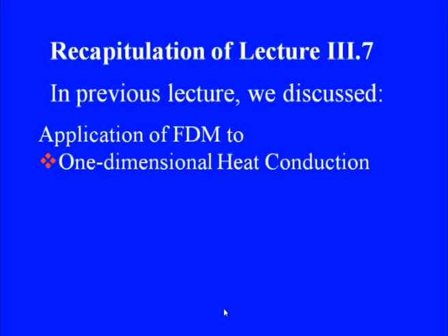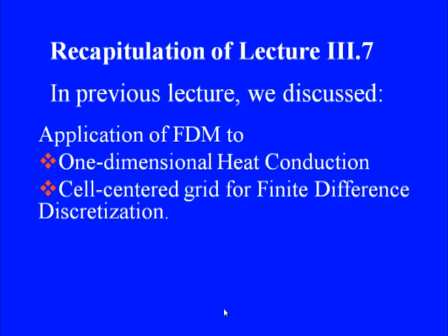Welcome once more to our lectures based on application of finite difference method to scalar transport problems. This is our module outline, and we had been working on the last topic, that is applications of finite difference method to scalar transport problems. In the previous lecture we discussed application of finite difference to one dimensional heat conduction, which was based on what we call node or vertex centered finite difference formula.